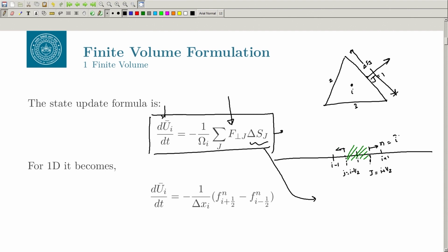Here this I is basically the unit vector i j k along the coordinate axes. This represents the x direction. In fact, I should write it as 1 0 0, to avoid this nomenclature. So, n is nothing but 1 0 0. That means unit normal in the x direction, and because it is 1D flow there is nothing in the y and z direction. And on this side n is minus 1 0 0, because the area normals are always perpendicular to the interface.